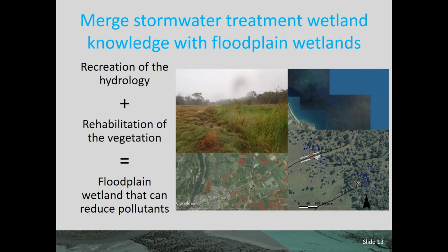So in a previous life, we did some work, and what we ended up doing was very, very simple, and this is where you can get a lot of bang for your buck. There were 2 big drains going through it, one draining this whole landscape that way, and this is what the drains look like. We ended up somewhat blocking those drains very crudely because we only had $5,000 or $10,000 or something like that, not a lot of money. That pushed a lot of the event flow out onto this floodplain wetland. And through there you had a lot of Eleocharis beds, so a very diverse habitat.